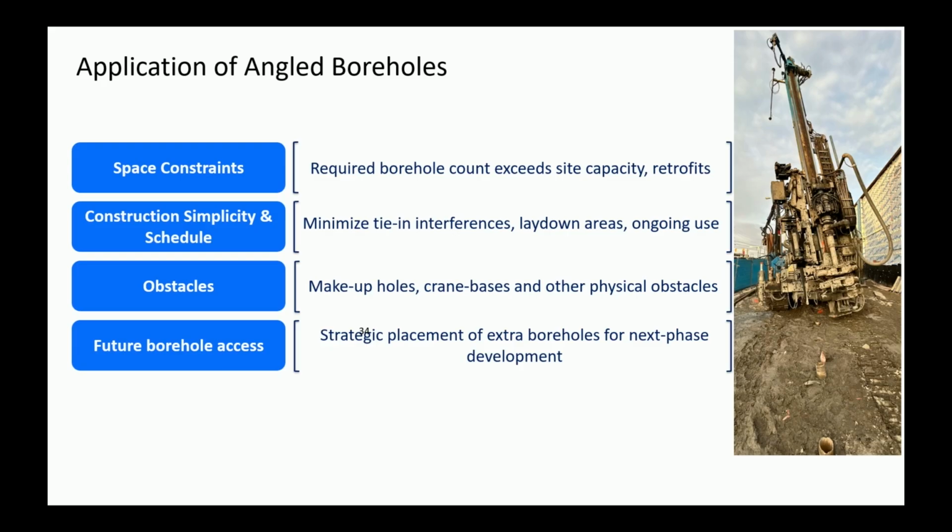So I'll talk a little bit about why angle holes. I think, Goran, you obviously hit that on the head about why. Space constraints, so we can get a lot more boreholes in a very small location and spread out under an awful lot of ground. The reason we really want to do that is often in cases where you have obstructions on surface that you just can't get to. So existing buildings, utilities, trees, all that kind of stuff.